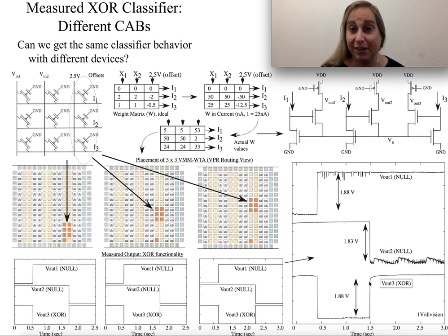Here's the interesting thing: I can take this in all these different spots, and because it's just a matter of making this matrix look ideally like this, to reprogram it, I can take it done in 3 different places and reprogram it and then modify that to give me all 3 of the XOR patterns perfectly as I would want. It's one of the beautiful things of the floating gate elements: not that I've just created a single pattern, but that I can create it anywhere.